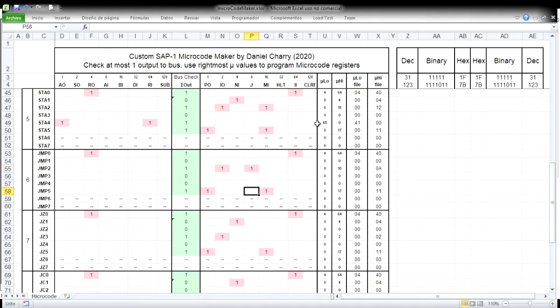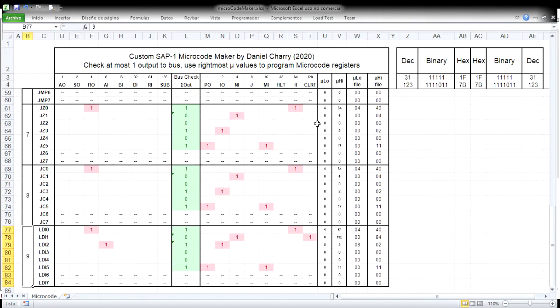You can see that the microcode I implemented does the program counter update at the end of the instruction. So we have program out, memory in, which is basically prefetching the next instruction, so that when we load the next instruction, we can, of course, do RAM out and instruction register in. Now, the difference between this and the upcoming instructions, jump if zero and jump if carry, is of course that the jump word is not determined directly by the microcode. There's actually some logic inside it.